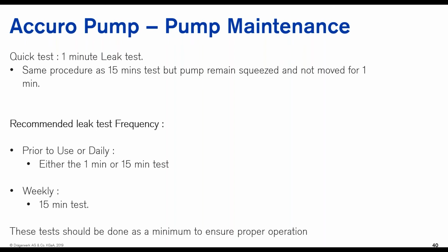So for the 15 minutes, when you squeeze and release, during these 15 minutes, the pump will start to revert back to the original position. But during the 15 minutes, it should not revert back fully. But for the 1 minute, it should not move at all. So for the 15-minute test, you can actually do weekly. So this test should be done as a minimum. This is to ensure that the pump itself is in proper operation and actually meets the proper requirements.